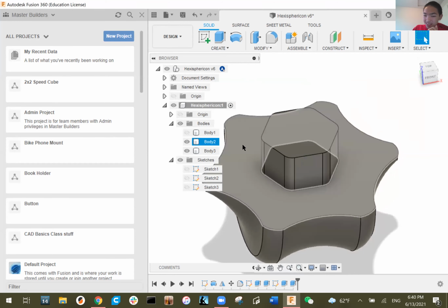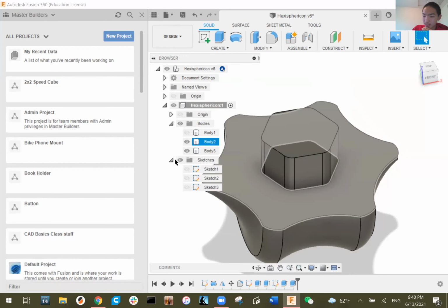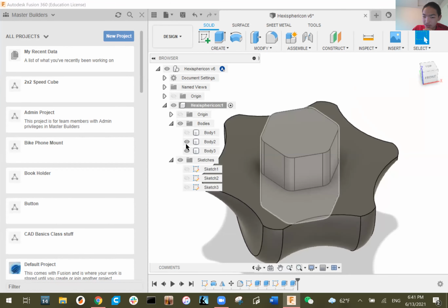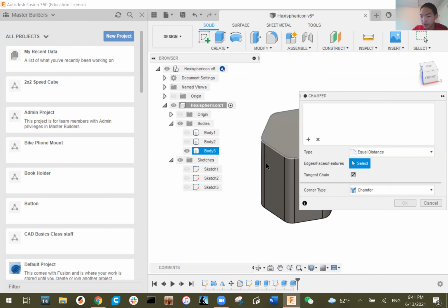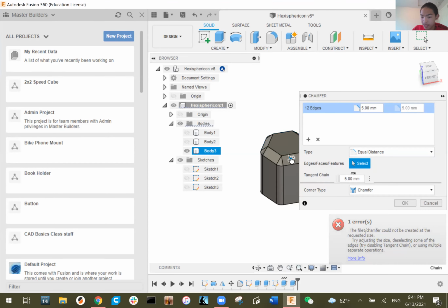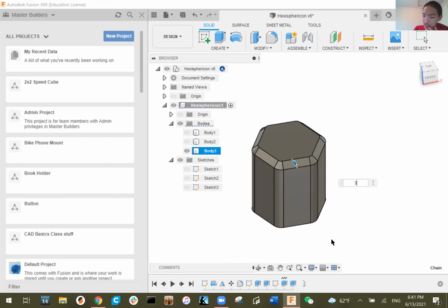So next, we're just gonna do some other tricks to make this easier to print and to attach together. The next thing I'm gonna show you guys is something called chamfer. Basically, fillet makes a round corner edge, and chamfer makes it like you cut off the edge. We can make it 5 or 2. I'm just gonna do 3 millimeters, and you can just chamfer the side.